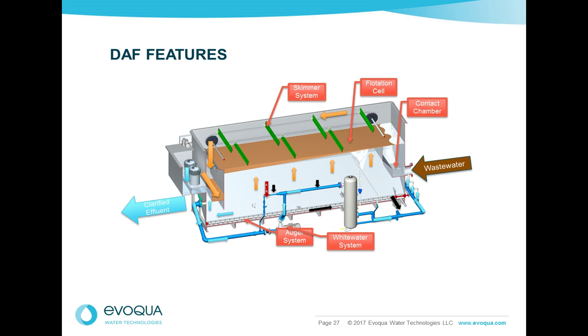Illustrated here is a recycled whitewater system that uses the clarified effluent exiting the DAF as the solution stream. As that whitewater is being generated by the pump and the air injection, it's being introduced into the contact chamber where it makes contact with the influent solids coming in.